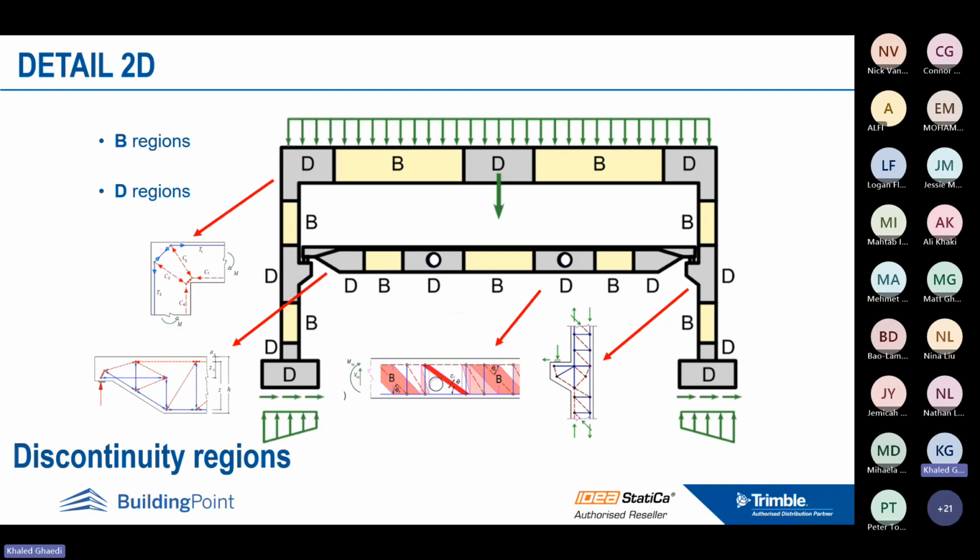And this is the place of pain, where we cannot design this kind of region in the conventional solutions. So either you need to use an advanced finite element solution like Abaqus or ANSYS, and later I will give you more information about this. Or you need to go through the conventional method like the strut-and-tie method. And each of them has, let's say, their own limitations.